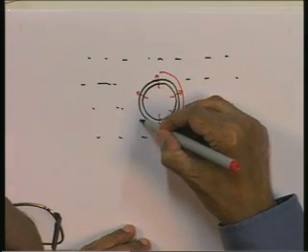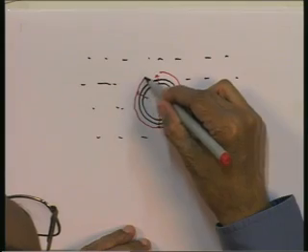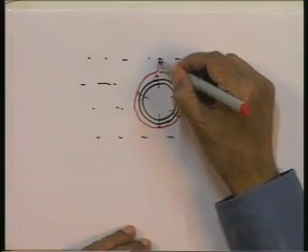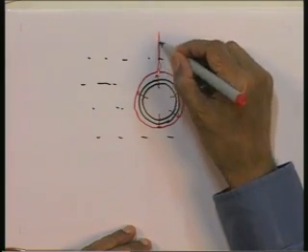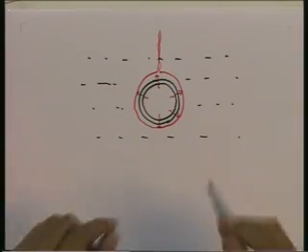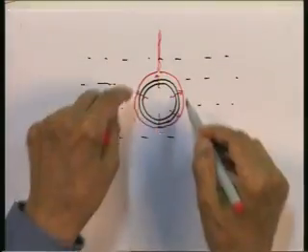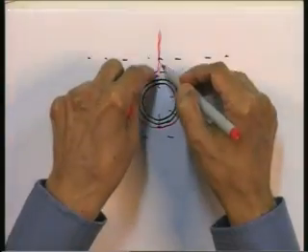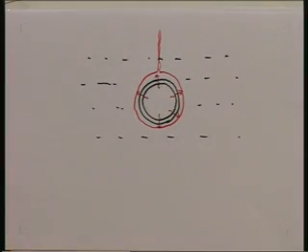We will get a film of vapor like this forming around the tube, flowing upwards because the density of the vapor will be less than that of the liquid. So, this is vapor flowing upwards and then forming some kind of a pattern as it goes out of the liquid upwards. A film of vapor all round the heated surface, the film of vapor rising and then going up as a plume at the top. That is what you will get.